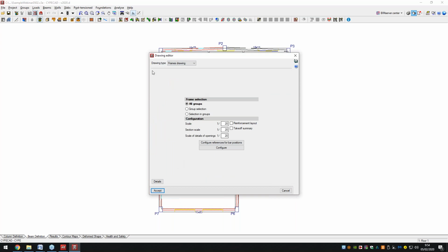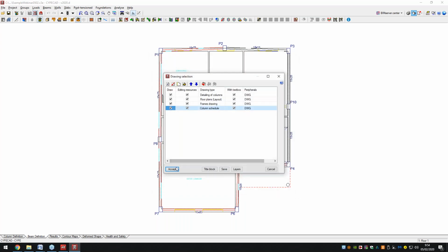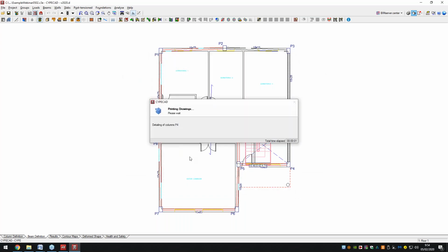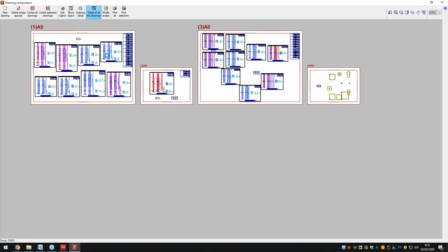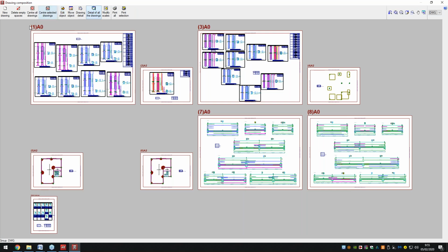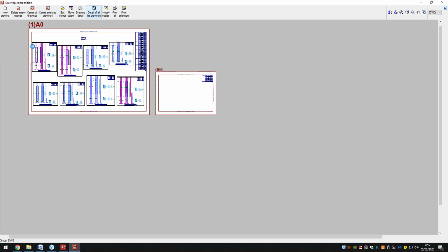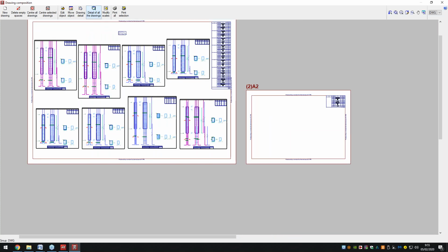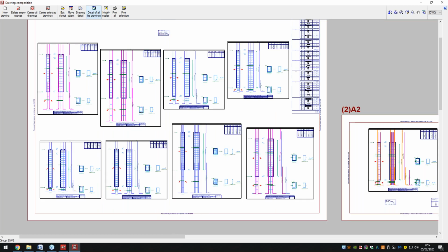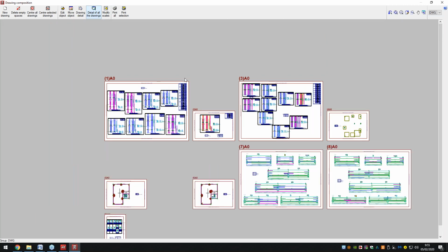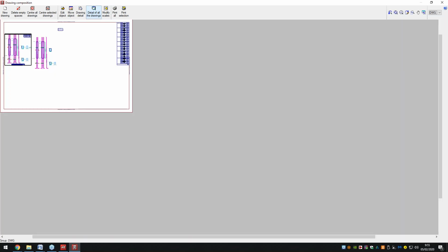Again, I have the option to configure all these different reports to a very high degree. Let's just keep it at that. And you can see, as easy as that, I'm able to generate the different reports here as well. So you can see my column schedule, along with the different reinforcements that are present as well. Again, these can all be saved and printed and shared with project collaborators as well. And these are my beams as well.